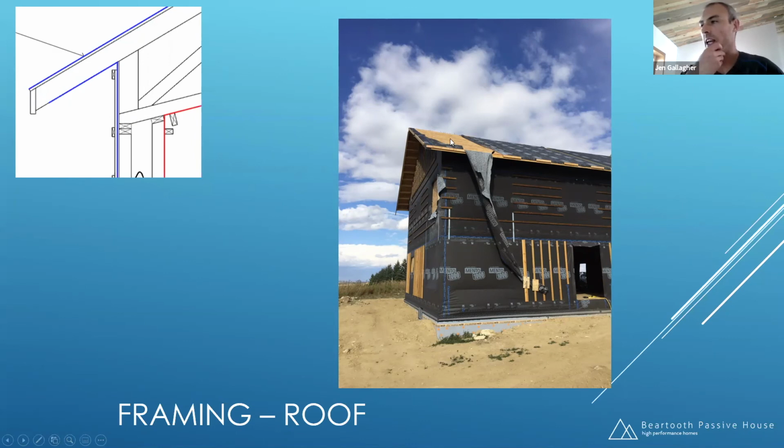If I were to do it again, I'd seriously think about a self-adhered roof underlayment, because that wouldn't happen, especially where we're at. If you're somewhere where it's not really windy, it's probably not that big of a deal. The cost is probably quadruple for self-adhered versus your traditional underlayment.